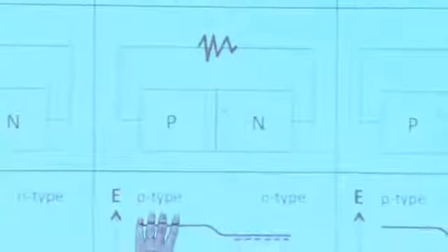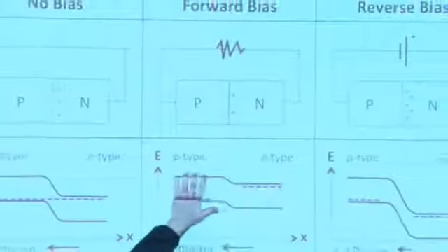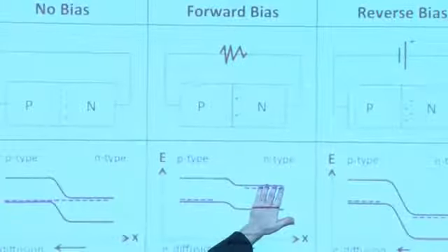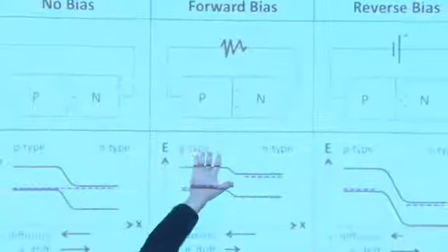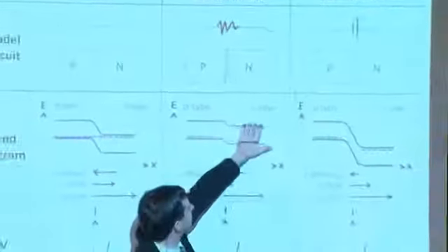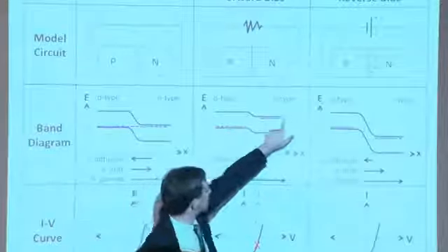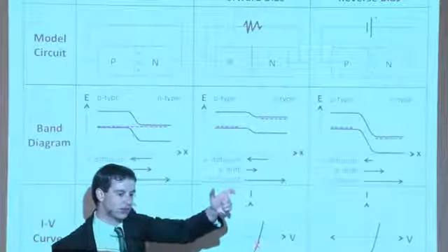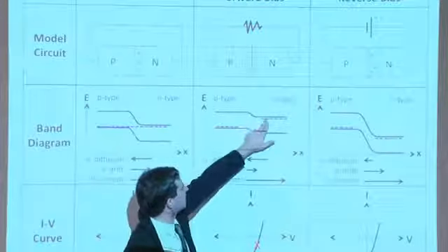Okay, so now I have my resistor here, and my illumination is coming into the device from, say, one of the sides. It's generating electron hole pairs. I have a multiplicity of electrons that have now gone down the hill, right? It's more energetically favorable for these electrons to be on the other side. And what has that done? That's raised the chemical potential this side. It's difficult for them to get back the other way. It's not impossible, but it could be more easy for them to flow through an external circuit to get back to the other side. And as they flow through that external circuit, they're depositing their energy across that external circuit. What energy? Well, it's the potential difference from this side to that side.